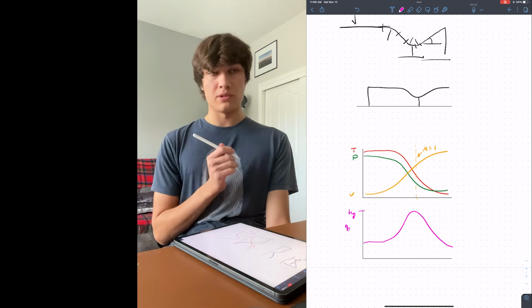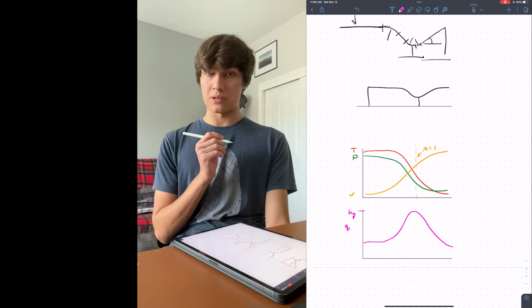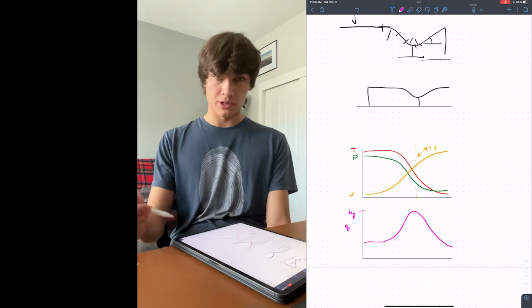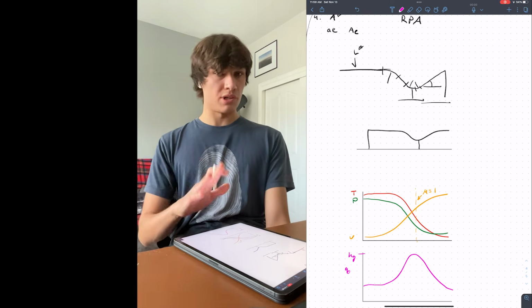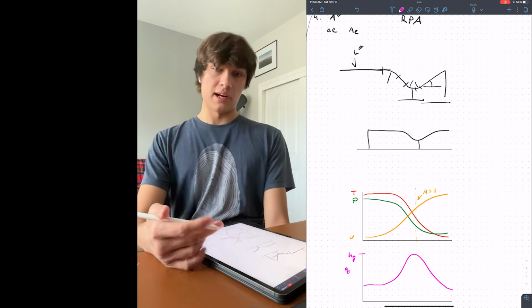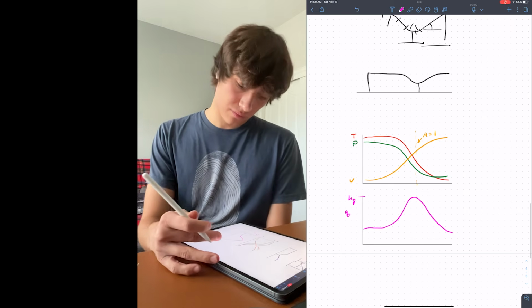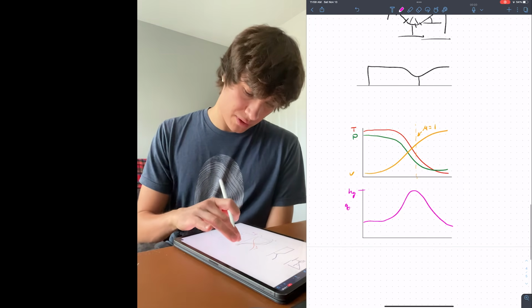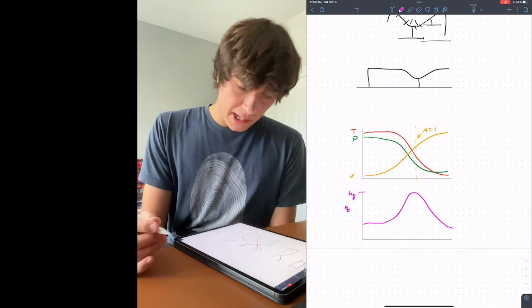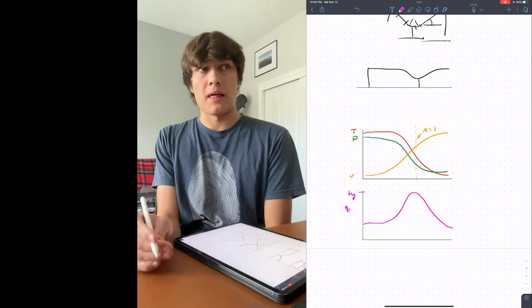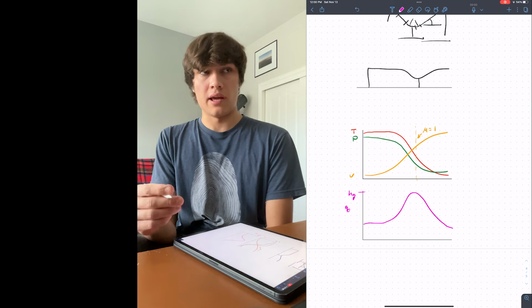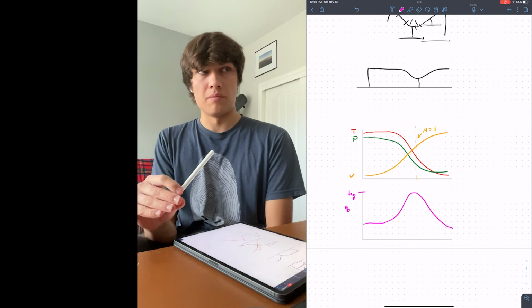The rocket configuration visualizer implements this code, and you can go plot this curve for your engine, or you can go to RPA and it will also implement this or a different estimation as well for you, and you'll be able to see what the heat transfer is for your engine. The heat transfer is really important if you're designing a regenerative jacket, and it is somewhat important if you're designing an ablative engine.